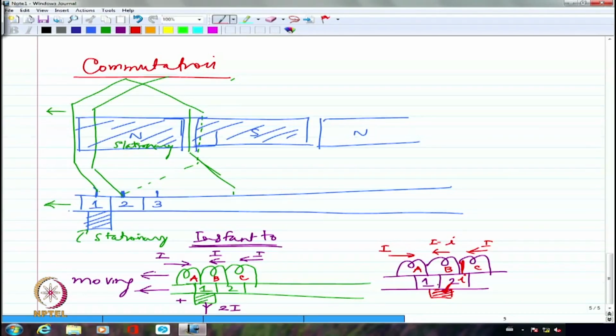But the problem with this coil is it is not very sure whether it is carrying the current in one direction or the other. That is the problem. So, I am going to see that this is going to be 2I. At some point, maybe the brush will make equal amount of contact with 1 and 2, both of them. At which point, it will actually see that it is collecting this small i equal to probably capital I itself. Right?